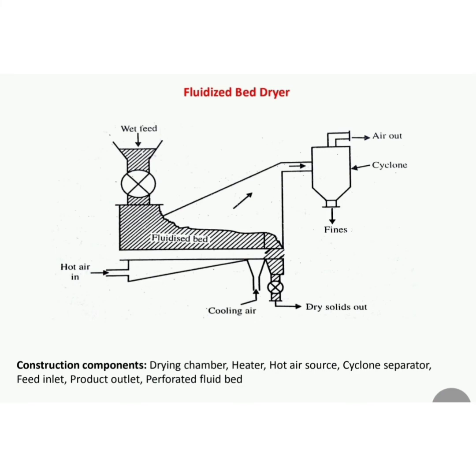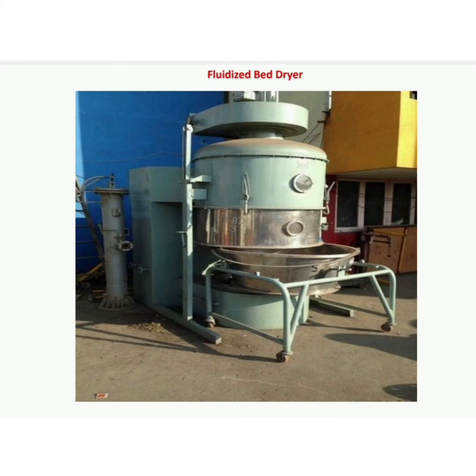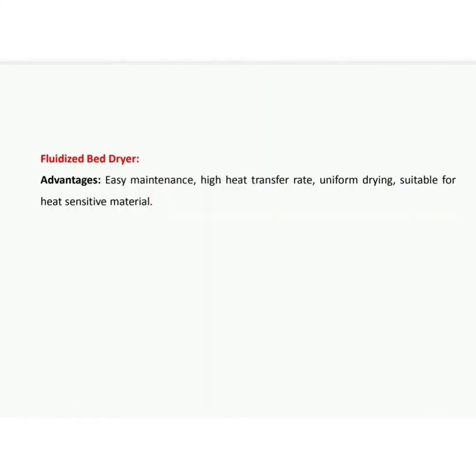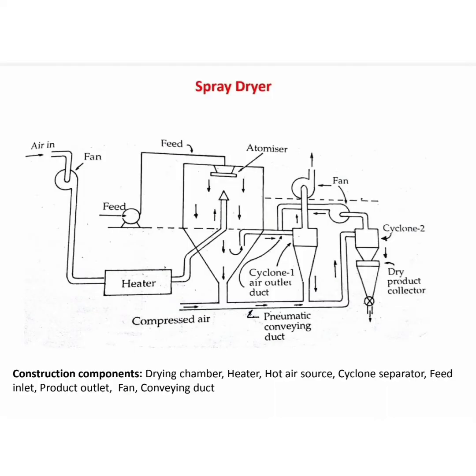Fluid bed dryer is used for drying very fine size free flowing materials. A typical fluidized bed dryer is as shown in the picture. Advantages of fluidized bed dryer: easy maintenance, high heat transfer rate, uniform drying, suitable for heat sensitive materials. Now let's see spray dryer.